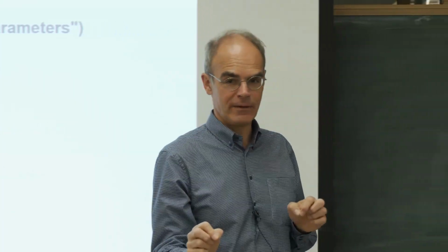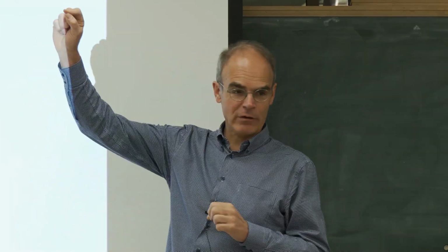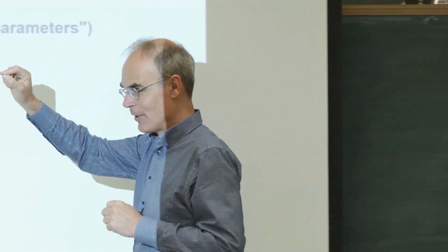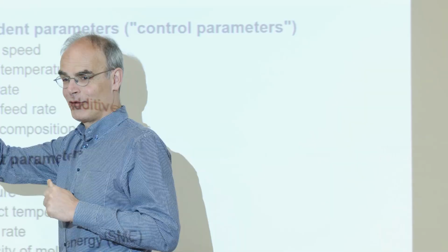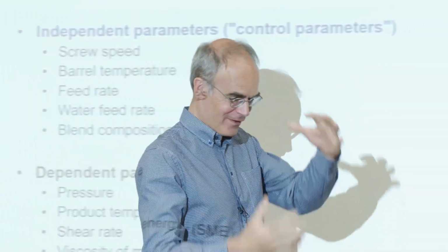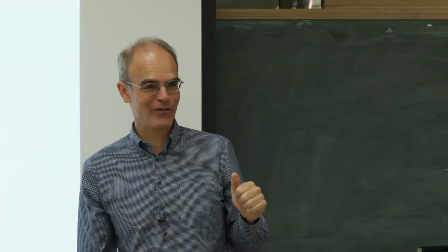It's also for safety, because at some moments you can get runaway pressure. I've actually run extrusion processes where pressure goes up way beyond 250 bars, which is a lot of pressure. That's more than the gas in these flasks that you have in the lab. They max out at about 200 bars, I think.